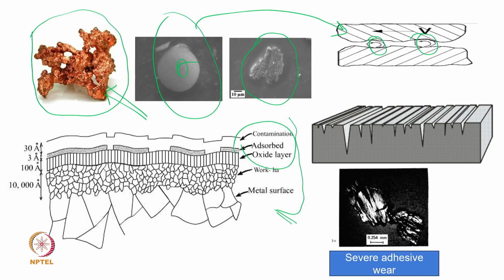of information to us. Now, look at this wear debris which has also been presented in a previous lecture. In this case, you can see the wear debris size is almost a mm. We have already presented that if the wear debris size is more than 100 micron, of course, everything is relative. If the size of the whole system is much smaller, naturally I will say 10 micron itself is much bigger, but as a thumb rule, if the particle size is more than 100 micron, that means it is significant, and the material or the surface is going to degrade much faster. So, that is what we call severe adhesive wear.